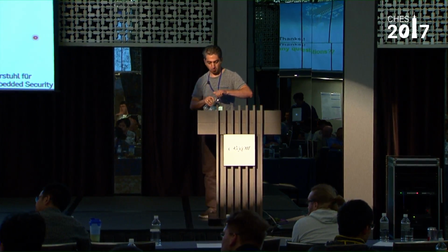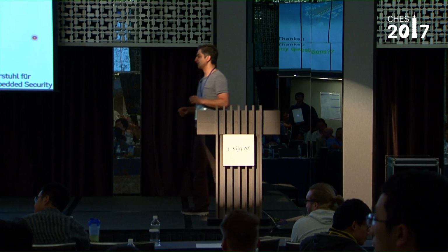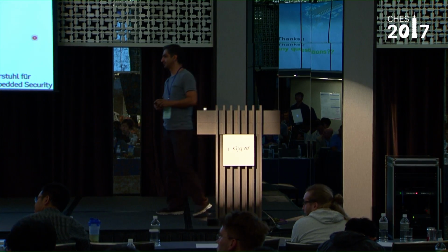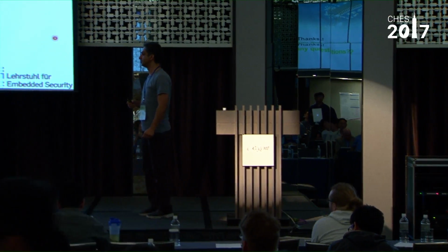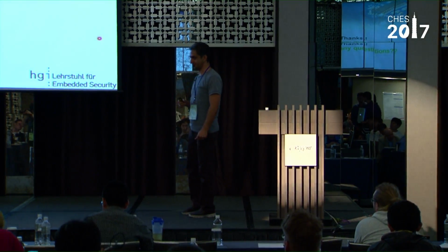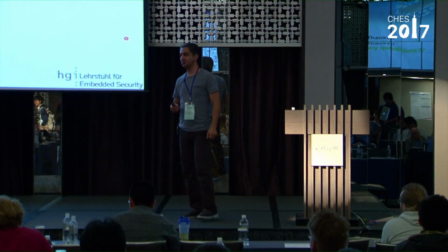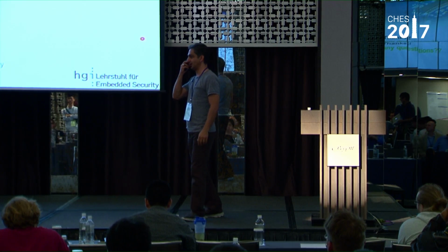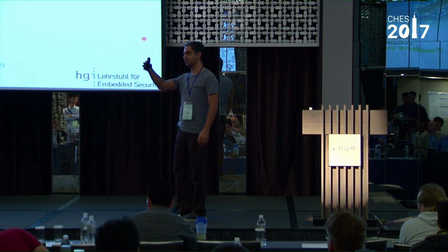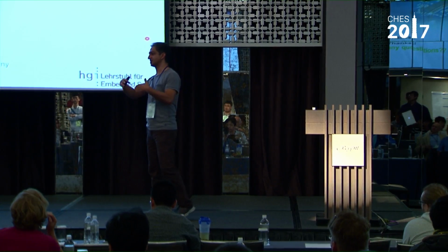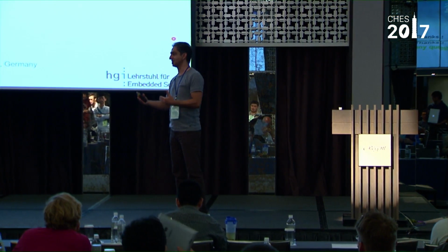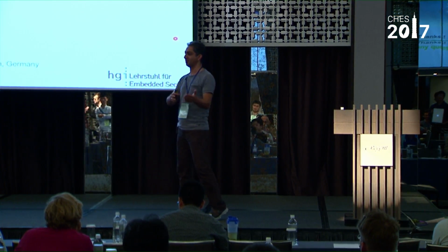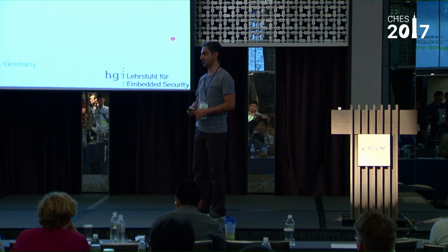Thank you very much. Are there questions for Amir? There's one there. Thank you for the talk. Did you consider using latches instead of DFFs to reduce the design again? No, we have not considered using latches instead of flip-flops. If you want to get to the reason, we probably need to talk very long, because it's a matter of digital circuit design. Why not flip-flop? Why not latch? But we have not considered latches, no.